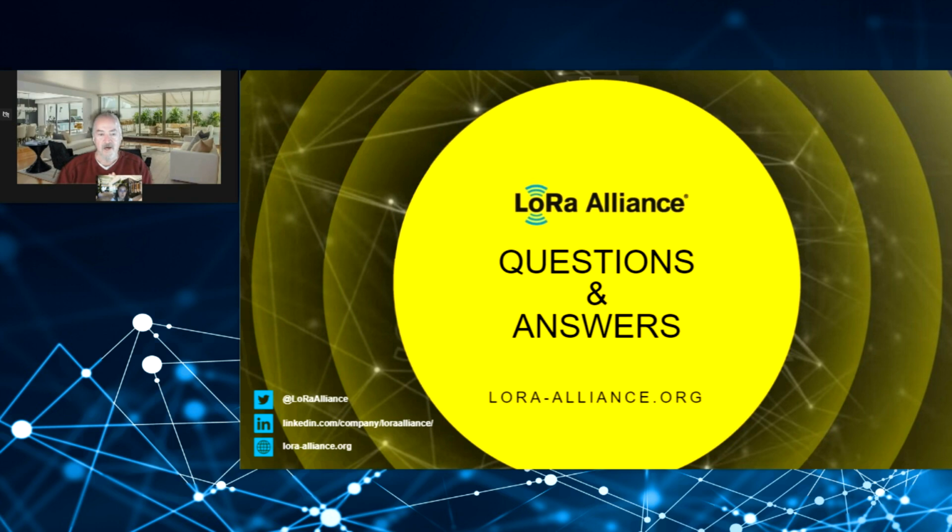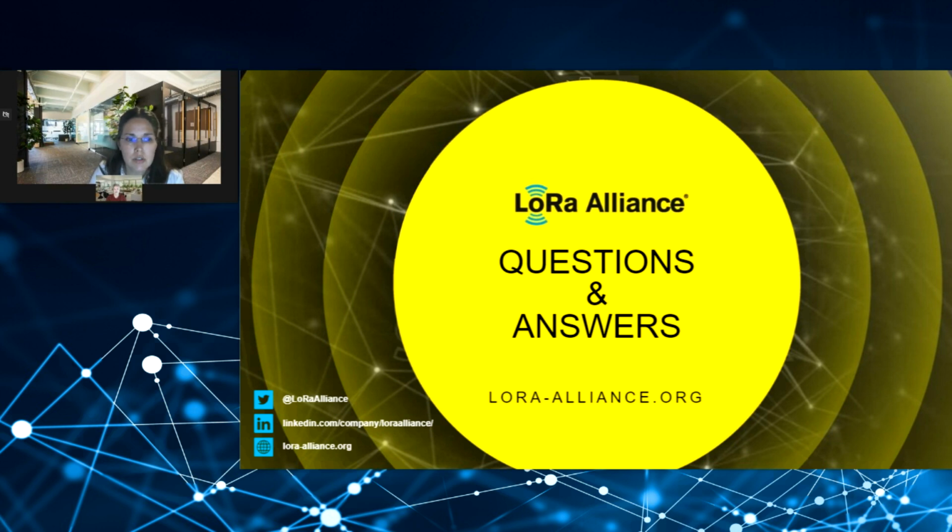Let's start with the first question. How should I prepare my device for retransmission back-off testing? Oh yeah, so this is a good question. So actually, important to remark, so retransmission back-off testing is necessary for version 1.0.4 and only if the device supports over-the-air activation. So in this case, actually, you don't need anything special on the device. So the certification port, for example, is not used during this testing. So the only requirement is that the device should start the join procedure each time it resets itself.